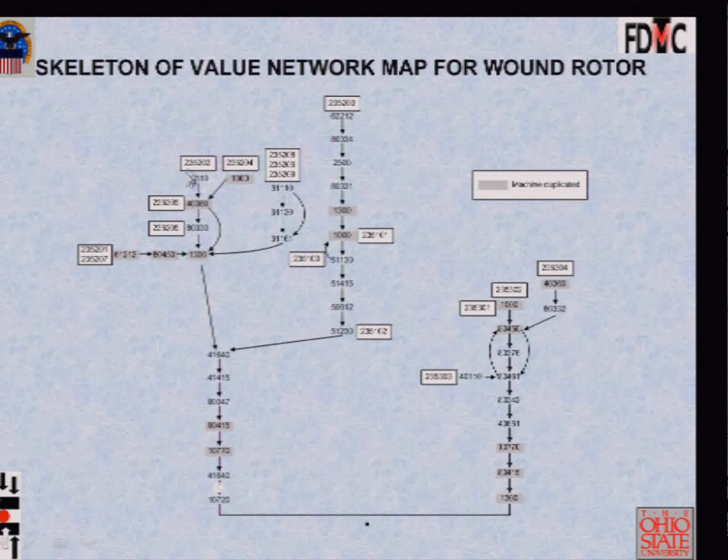That's the component numbers here. And what we have done is we have merged those routings into what we call from-to charts or spaghetti diagrams. But automatically you can see there is so much commonality of work centers. Look, 8415 is here, 8415 is here. There's going to be some competition when those two sub-assemblies hit. Work center 10770 is also used here, 10770, right? So you can see there's going to be competition.